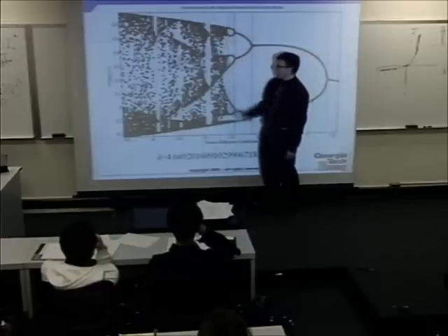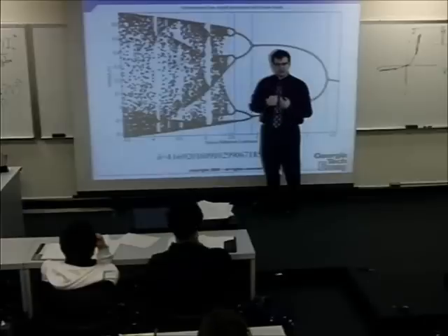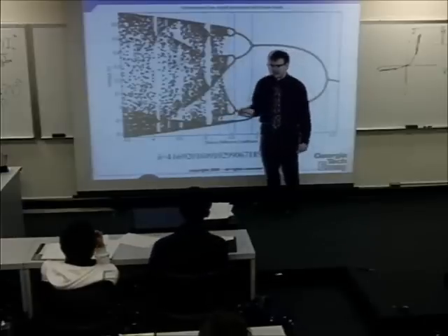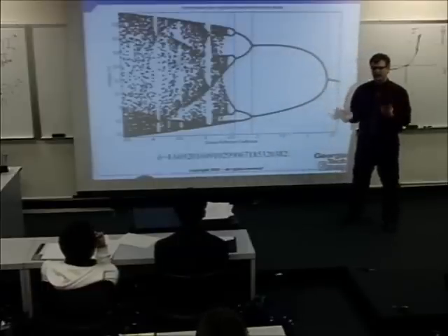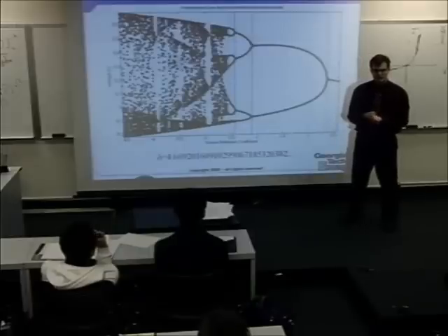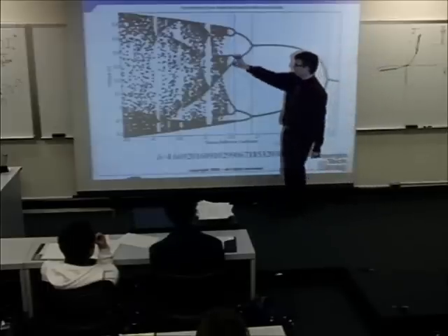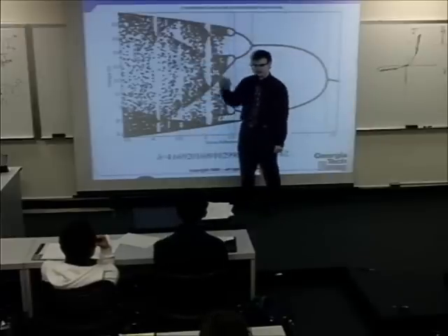And finally, there's a wall, a geometrical limit that you approach, where the system becomes chaotic and it basically does not repeat itself. This is actually a really interesting circuit. There are lots of chaotic circuits out there, and they're very interesting in the fields of cryptography, of authentication, and identification, of random number generation, because they exhibit something called sensitive dependence on initial conditions. In other words, this solution will jump around in this region. If I pick a value and just stick with it, it will jump around and never repeat itself.